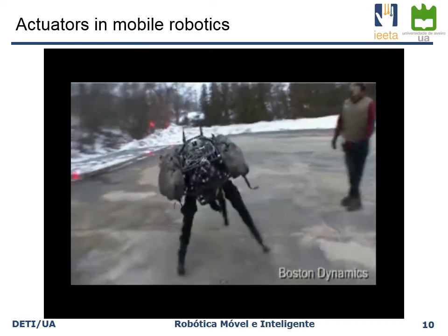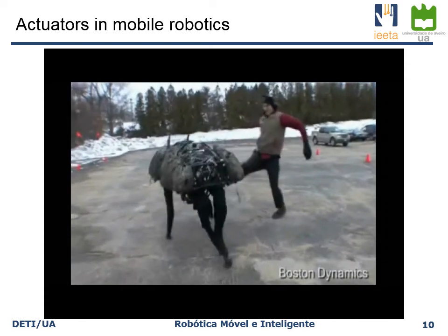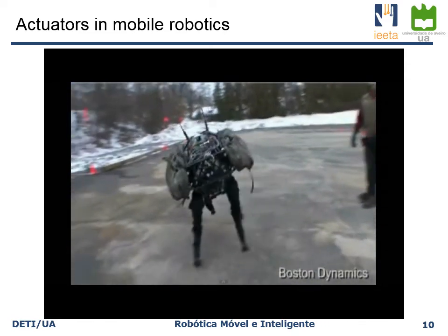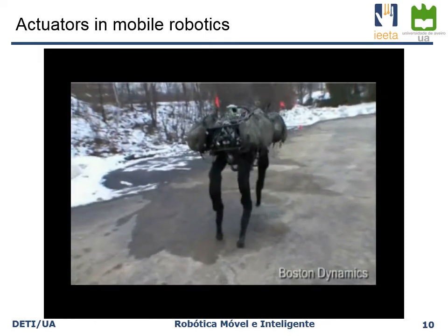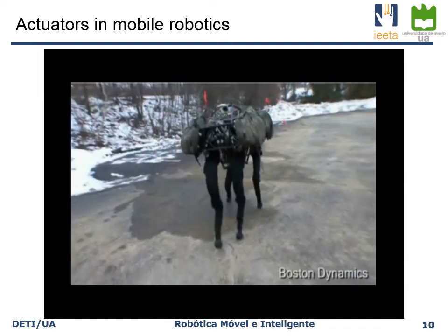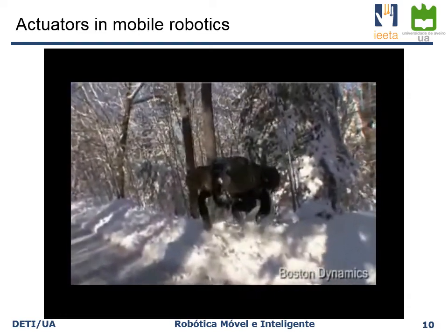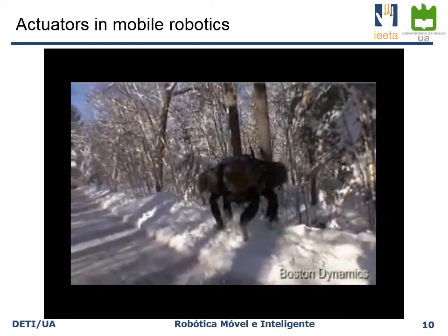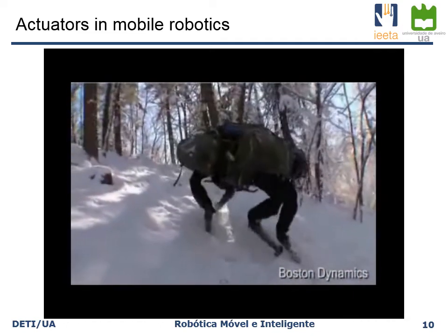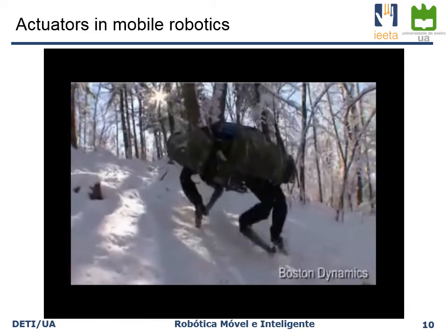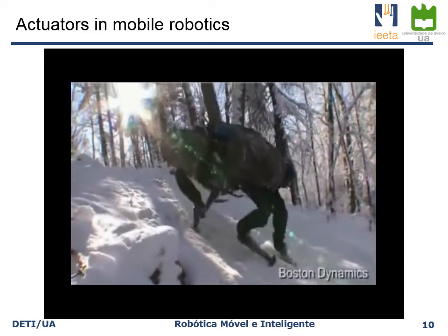In this slide, you can see an example of the Big Dog, and namely the level of control that is required to ensure that it does not fall on the ground. And it's amazing what they can actually do with this kind of device. The Go-Kart engine is on the top over here. Maybe you could hear the noise of it running. It's running at 9,000 RPMs, and it's generating the hydraulic forces required to drive the legs.